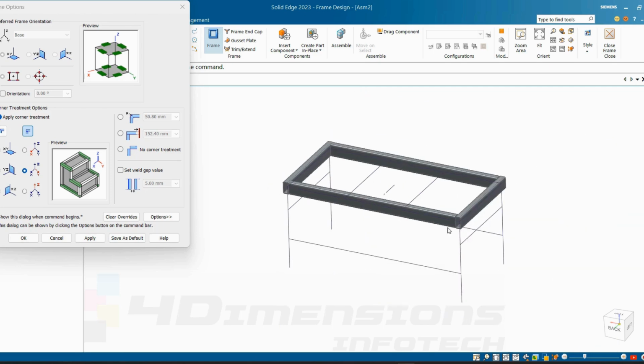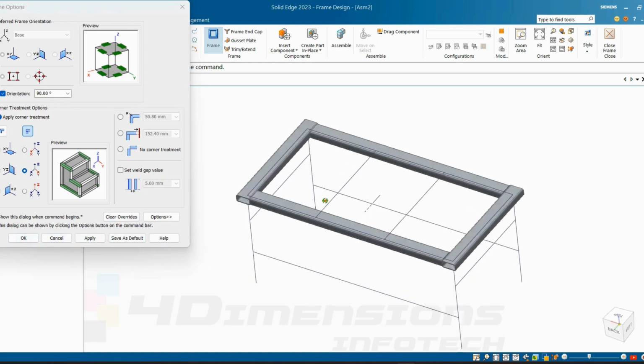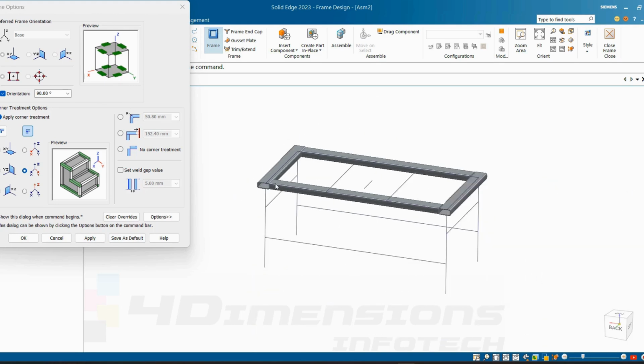And the orientation of the tubing is coming vertical. So if I want to make this orientation default instead of overriding the angles, I'll select this orientation from this chart itself, that is from frame options. Earlier we selected the orientation as customized for individual corners. This time I am selecting this condition from the frame options itself. So I'll apply this angle as 90 degrees from here only. Say apply. And you can see the end conditions are now making the pipes horizontal orientation.